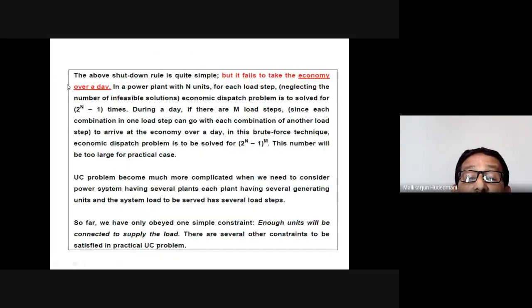Before going to that, let us look at the priority listing method. For a certain megawatt, from a step value to another step value, I can group the generators by priority, such that the machine I choose first is the cost effective one, lower in production cost, which produces megawatts from its minimum to its fullest capacity with a very effective cost of fuel.